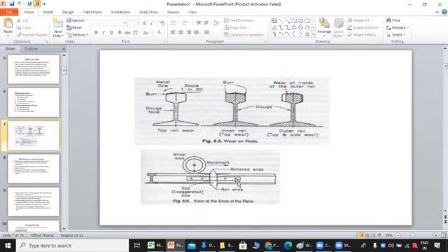So what happened, due to the continuous movement of rail, the continuous impact load acts on this particular section, and the stresses also act on this particular section. In such condition, if you see, these rail ends are damaged, that is nothing but the battering of rail ends.